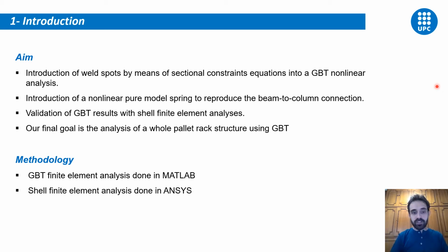The second objective is the introduction of a nonlinear pure model spring into the GBT model to be able to reproduce the beam-to-column connection characteristics. Then we want to validate the GBT results with a shell finite element analysis. Because in fact, our final objective in this research line is the possibility to analyze a whole pallet rack structure using generalized beam theory.